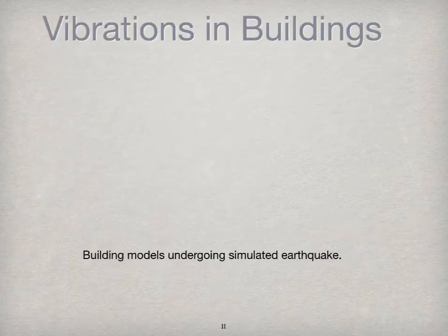Now, vibrations can be caused by nearby traffic or subways, building mechanical systems, or just simply normal human activities such as walking across the floor. This vibration does not jeopardize the building's structural integrity, yet while the actual motion may be minimal, human perception of motion is significant, and these vibrations can be disturbing to building occupants. I don't know, some of you may have been at some tall skyscrapers in New York City, and you can actually feel the building moving.